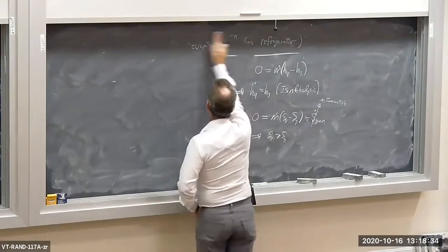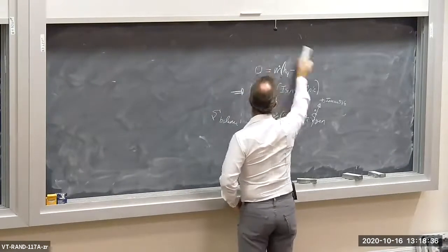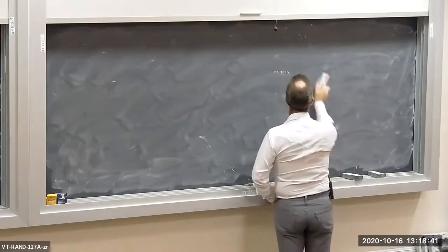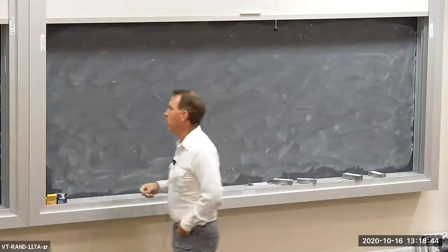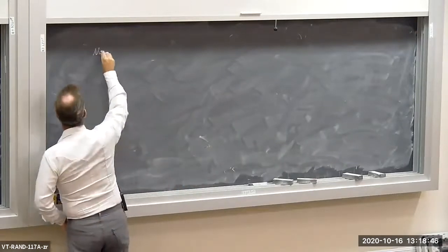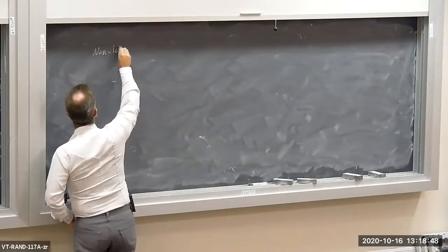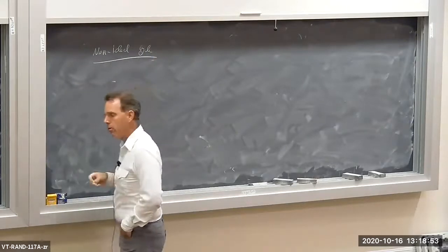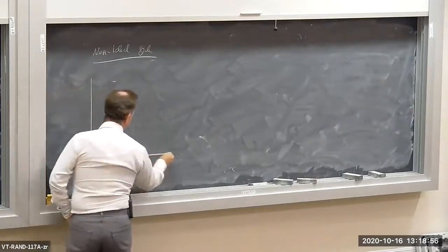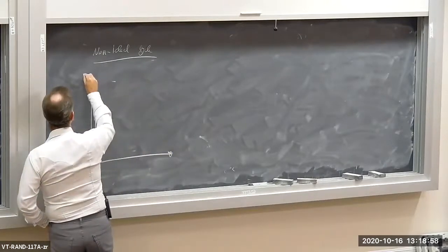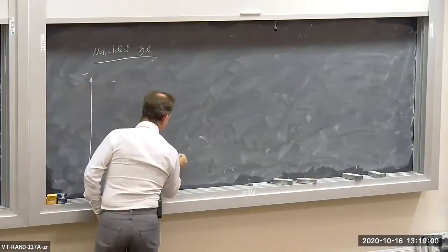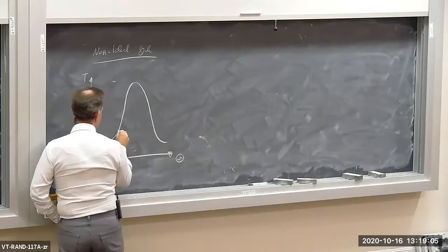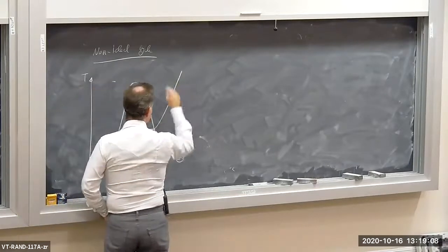Of course, the obvious one is having isentropic efficiency for the compressor being different than 1. So having irreversibilities in the compressor. So here's an example of a non-ideal cycle, non-ideal refrigeration cycle. So we could have a whole number of things happen. So this is T-S. Here's the dome. So here's our P min right here.